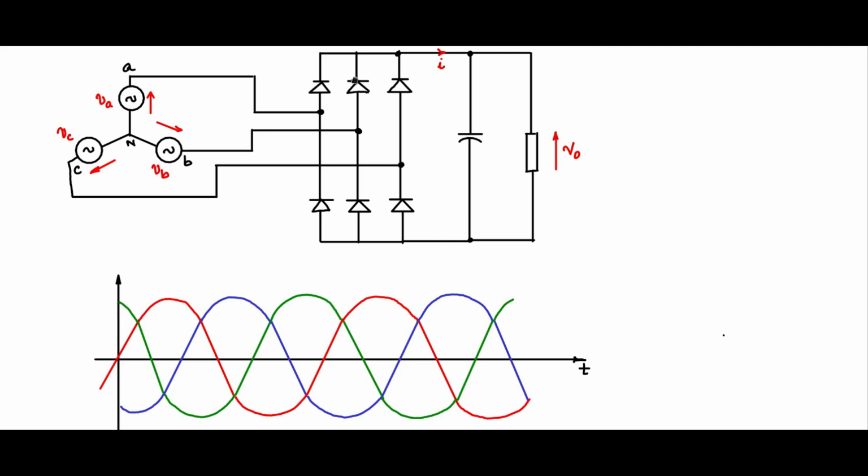And now when it passes through the rectifier, across this node, if the capacitor were not there, you will see that this will fold. This will be the rectified waveform, folded back, so I will show that in dotted. You will see that these bottom portions will get rectified in this fashion. And then look at this envelope. This is the envelope that you would see here, and this envelope you obtain even without the C filter.